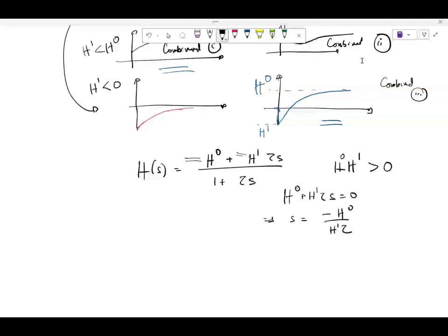But the argument against it, even though it's not a very strong argument, will be that the zero location will also be dependent upon the values of the C's, right? Or will it? It will, right? Because the time constants are dependent upon the values of the C's. So if I change the values, that cancellation might not work. No, I mean, we can obviously work backwards and come up with it, but it will not be true for a generic, for the same architecture.